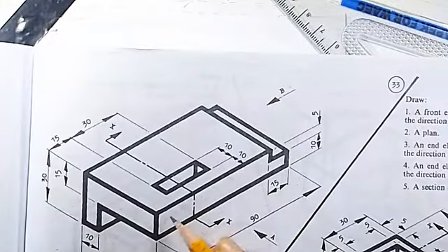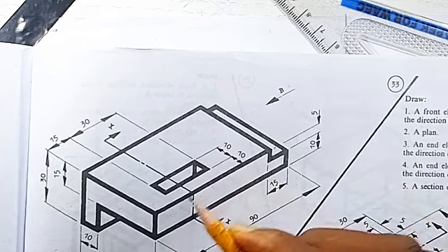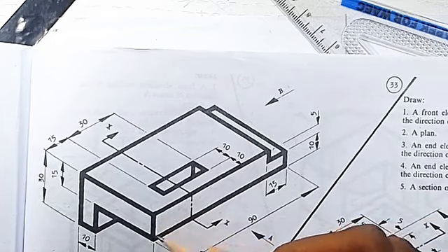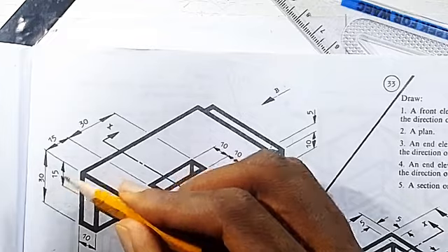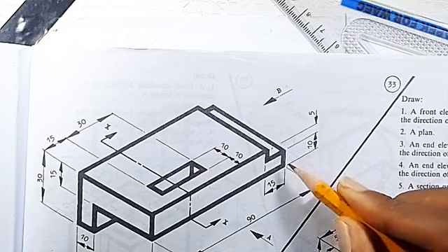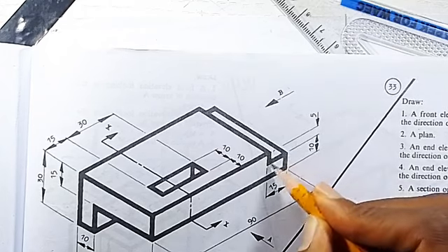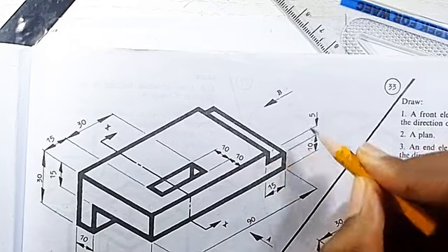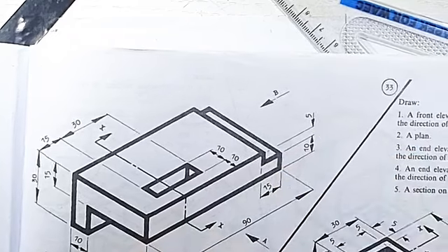After that, we have the top part, which is this part here. So we draw the height 1.5 cm, then take this part here by 1 cm. So once you draw by 1 cm, you project it to the left by 1.5, take it up by 0.5, and join it together. Let's do that.